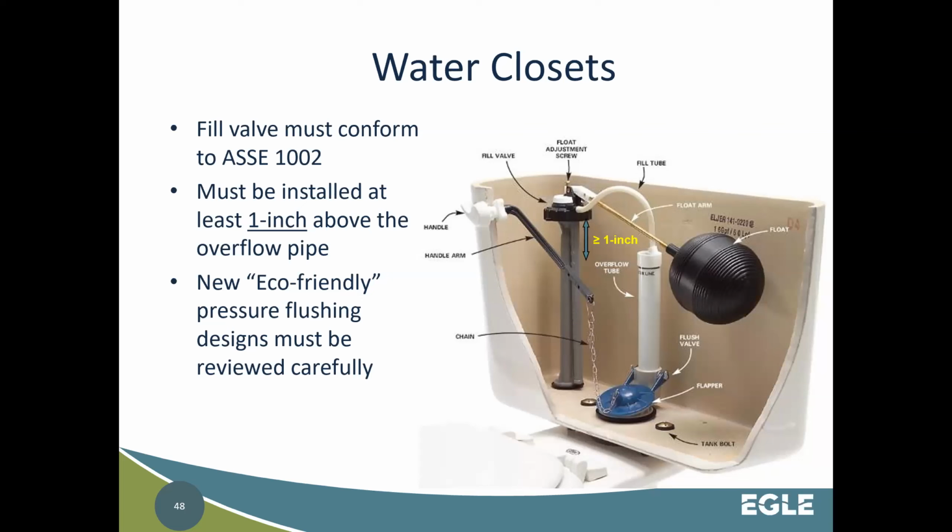But there's supposed to be a 1-inch gap from your fill, because this is how toilets fill, right? It flushes. This is your fill tube until it shuts here. There's supposed to be a 1-inch gap between the fill valve here and the drain overflow pipe here. I would be curious to know how many people actually open the back of a toilet and inspect this. My guess is probably not very many.